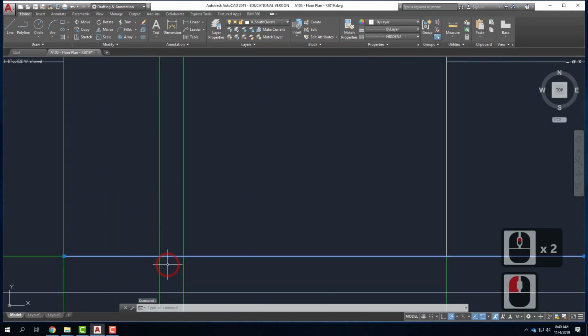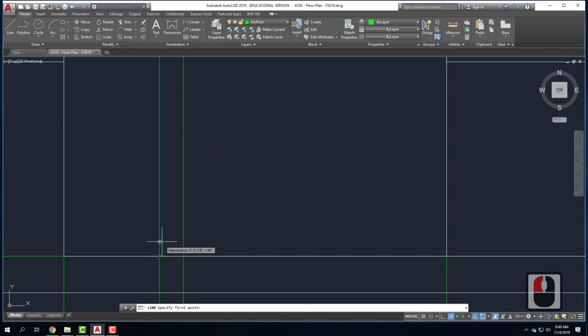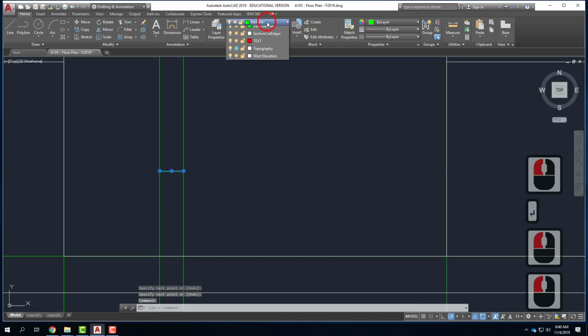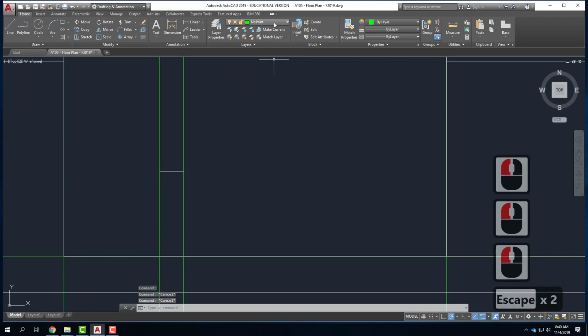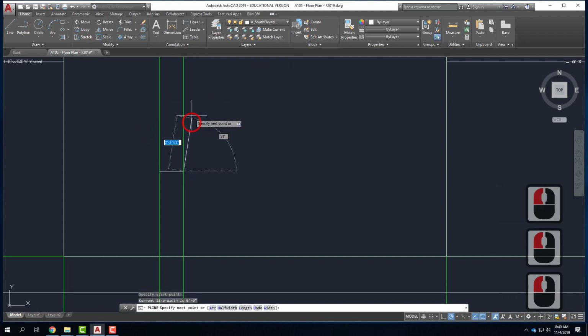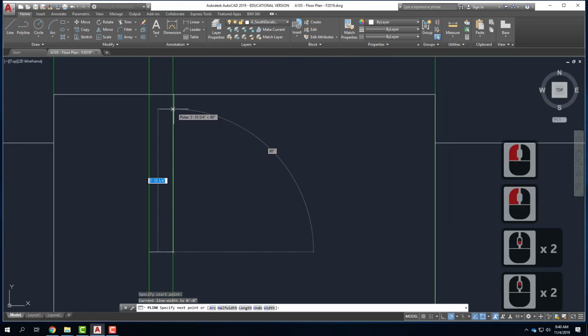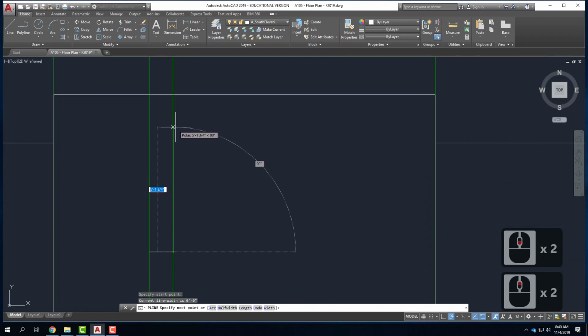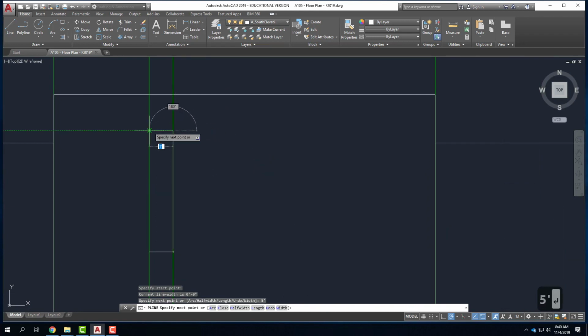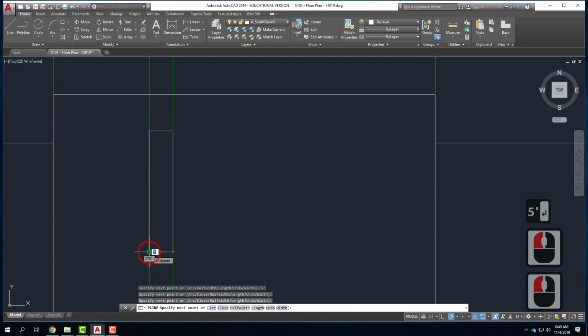So again, that's my floor. I have cabinets. My cabinets would be 3 feet tall. That's a standard cabinet. So I need to start my window above where those cabinets would be in the kitchen. So we'll do it at maybe 3'6". So I'll go ahead and come up here, 3'6". And that's my first line of the window. I failed to change my layer, so let's change that over onto the south elevation layer, and then let me change my active layer to be south elevation. And I can continue with my drawing here. So I have to decide how tall I want this window to be. Let's do a 5-foot window. We'll come over, and we'll come back down to right there.